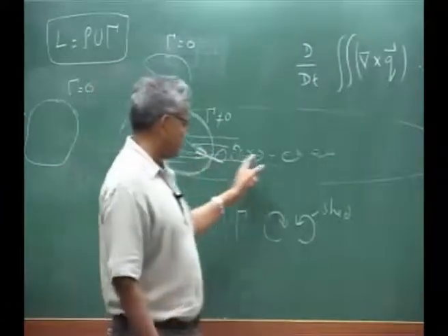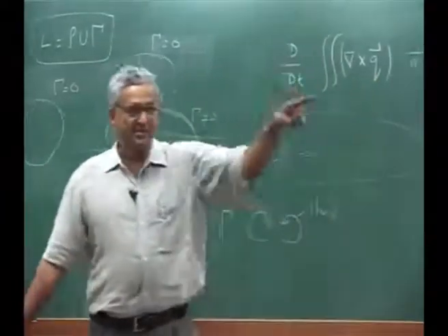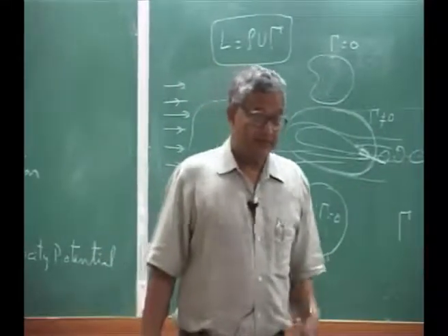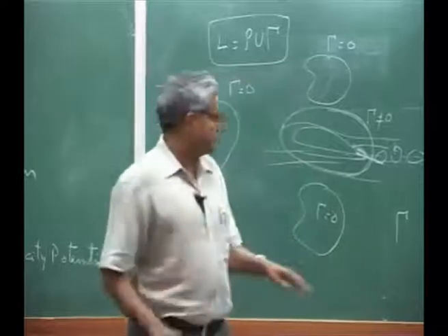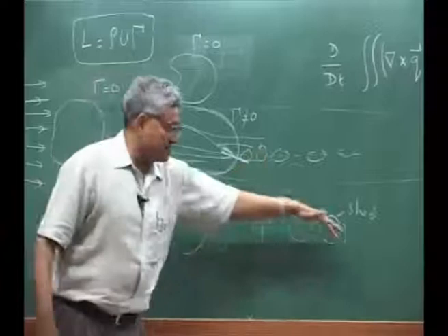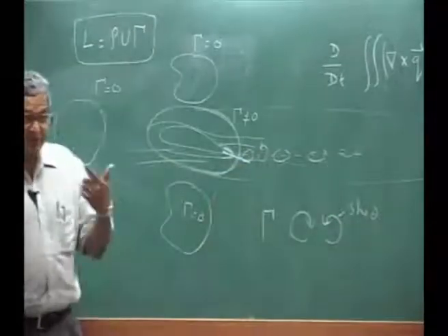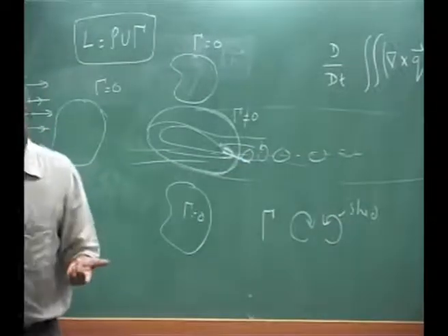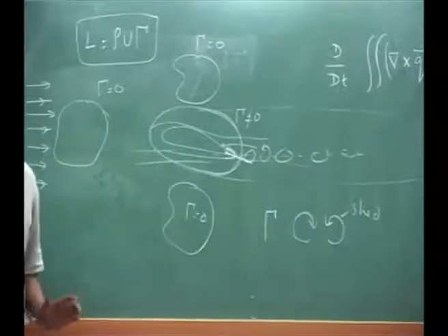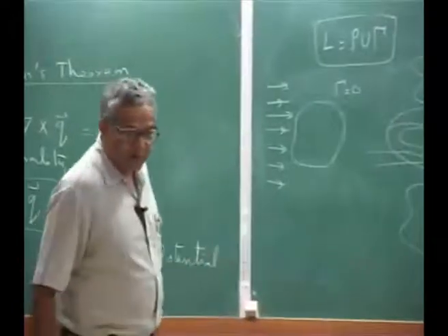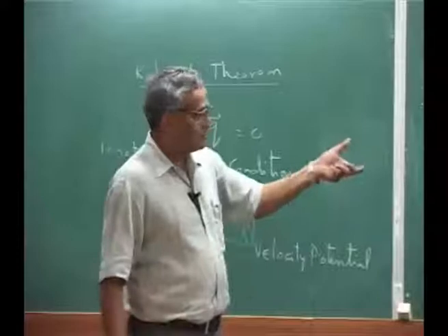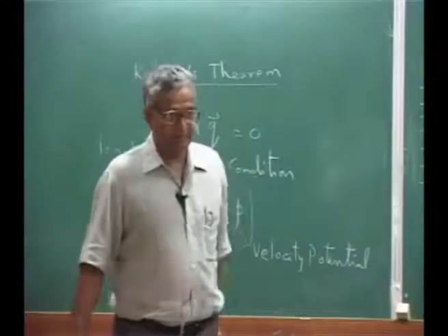That means the wake structure, I say it will be in a straight line behind the aerofoil. But if it is a free wake, that means I allow the interaction between these. That means they can interact, they can change the orientation and shape. Then computationally that becomes more complex. That's why free wake analysis and prescribed wake analysis, all these things are in potential flow. Okay. The only thing is the strength of the vortex you don't know. That is what you calculate later. Okay.